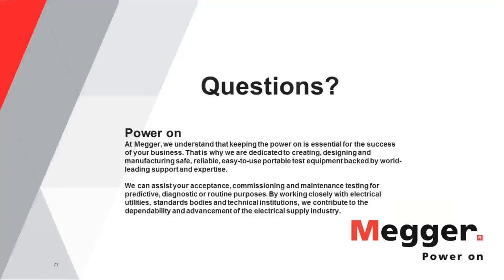Of course it doesn't. It may work fine for many years, but the company is trying to reduce the number of callbacks, service calls, where something gets installed and then the customer doesn't have satisfactory operation out of it. They call the company, and it's a costly service call. So they sat around a room full of people at one time or other and decided, okay, 100 megohms is a reasonable value, so we'll put that in the spec. Anybody working against that has to make that.